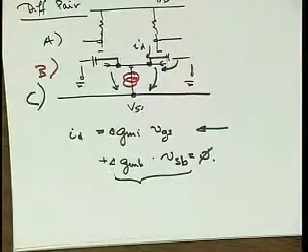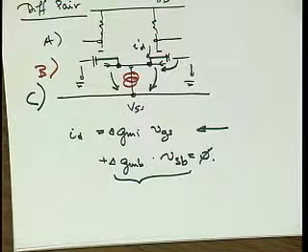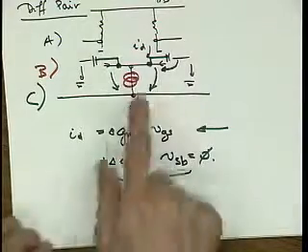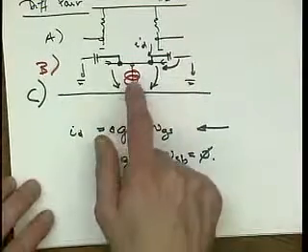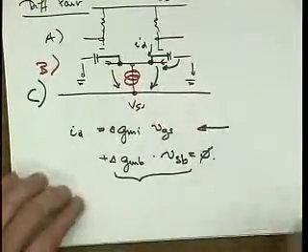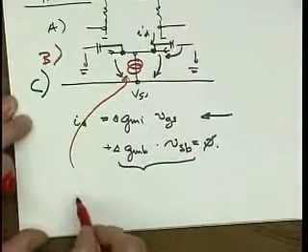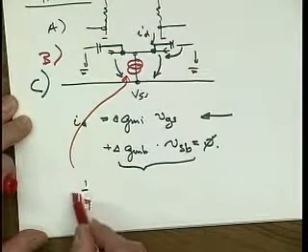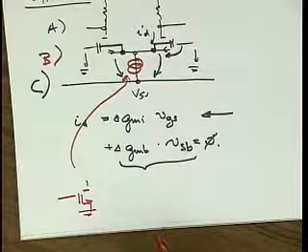For the 240 project, usually the answer is very easy because you are fabricating your design in SPICE, matching's perfect, and you can get arbitrary common mode rejection ratio with whatever you do. So you use an NMOS input that has higher fT, right? And you don't worry about it. Likewise, this current source here, very often it's just a simple one transistor current source. It will work that way.